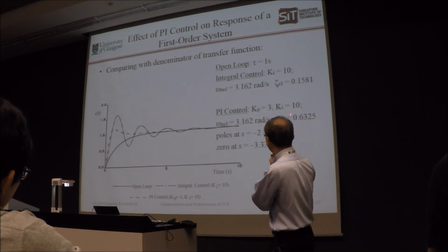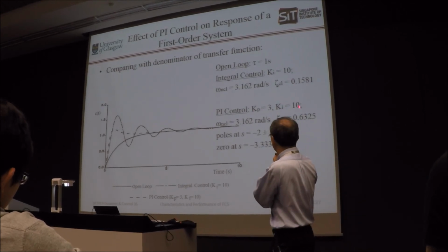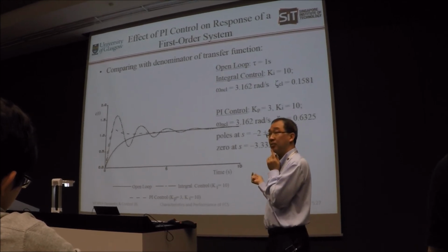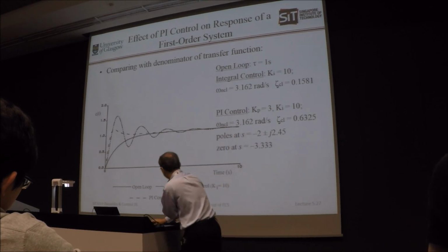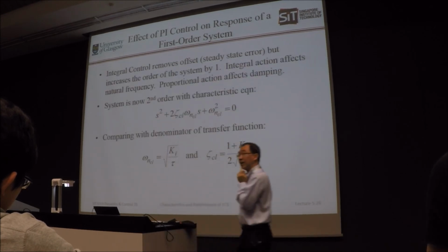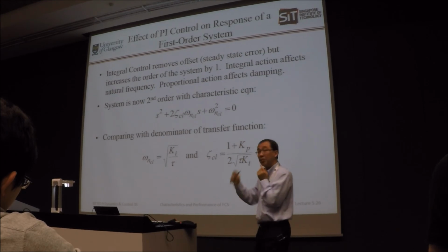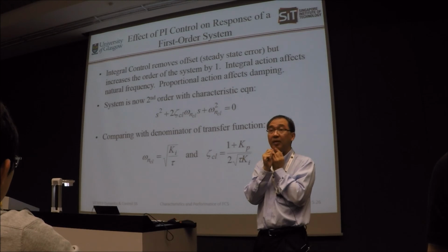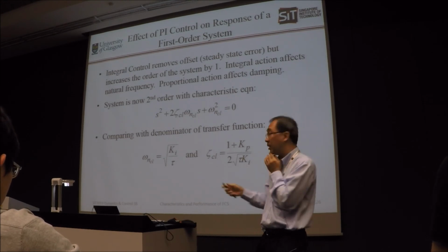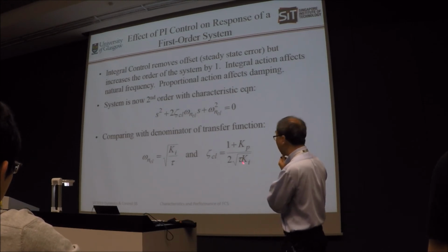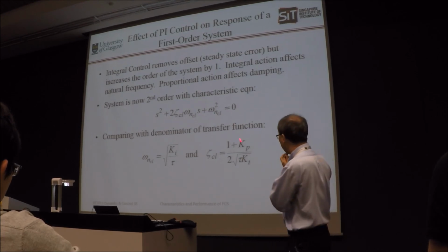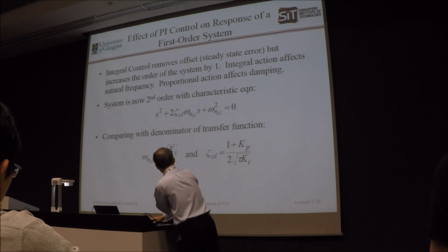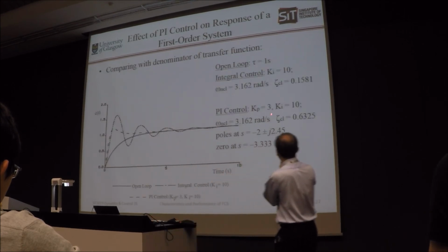Except that now, with the PI, you can actually see what happened to my damping. My damping can actually be rather large, and that is the effect we have seen from this exercise here. Using a pure integral control action eliminates steady state error, but at the same time, you don't have much control. Sometimes if your Ki is a large value, your damping becomes very small. But if you have a P controller or P control action, you can actually try to maintain your damping.